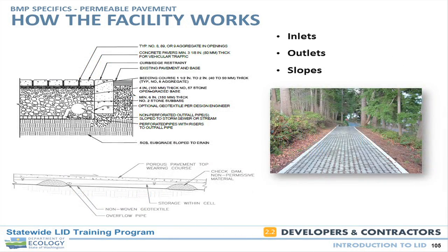I wanted to discuss this idea of slopes. Picture happens to be a permeable driveway that I did at Lake Whatcom watershed, and that little detail there where I've got the flush curb. The key is permeable pavements are not under-drained. So we set the pipe down in the gravel, it's slotted on top, but it's outlet controlled. So we do allow the subgrade to flood.